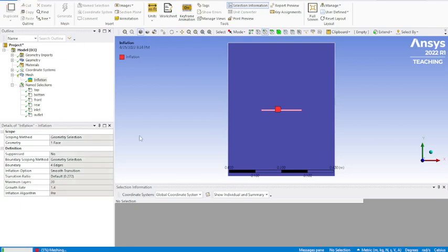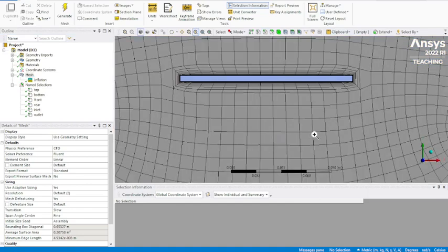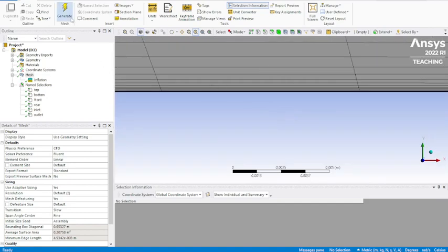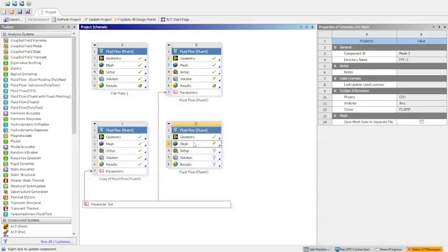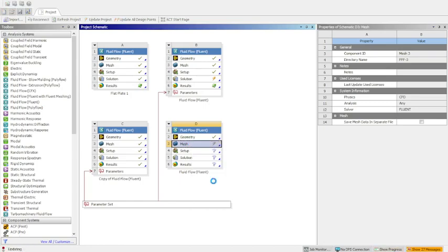This mesh will take a little bit longer to generate. If you have a faster computer, you can go to mesh, set the sizing a little tighter, increase these layers, but this should give us a pretty good view of what's going on in that boundary layer. Got that. We'll zoom in so you can see how it's a little tighter around the actual flat plate. That should give us pretty good analysis of the boundary layer. We'll update this. We'll double click on setup.